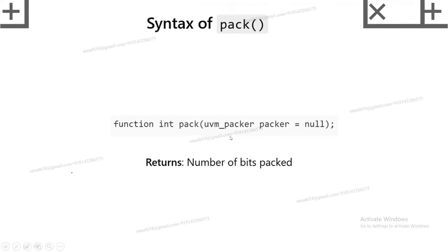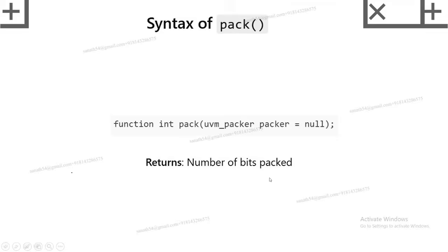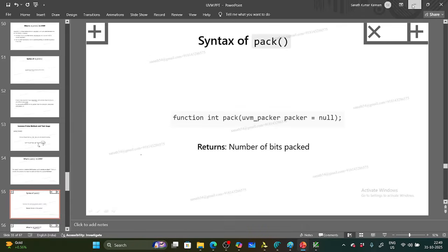This is the syntax for pack. Function int, so it will return an int. pack takes uvm_packer equal to null. That means it will return the number of bits packed, which is why it returns an int. We'll see one program related to pack.